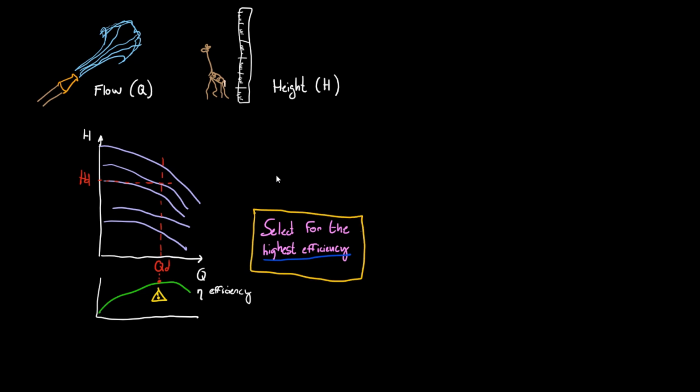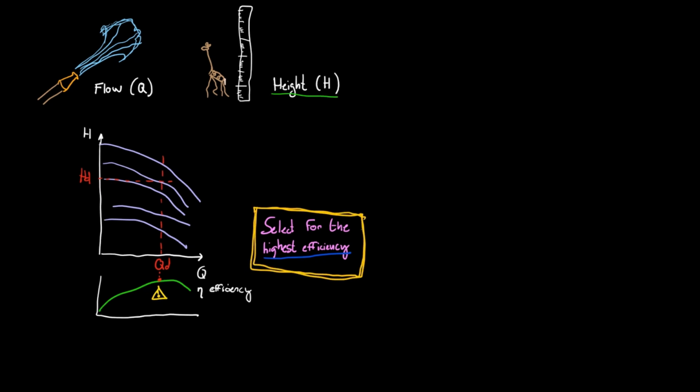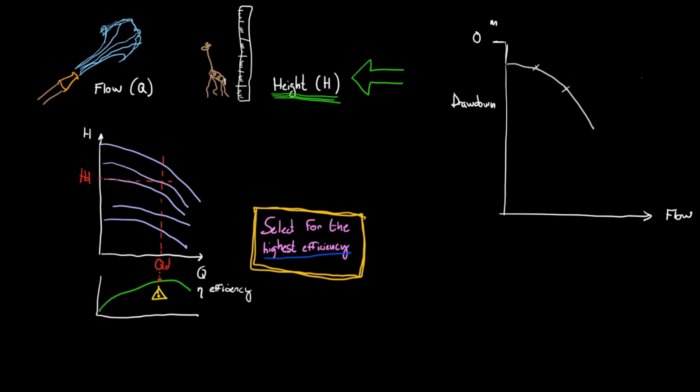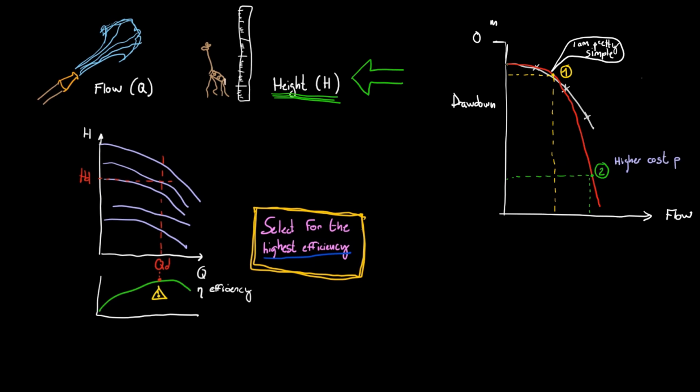The flow influences the head by either affecting the friction in pipes or the drawdown in boreholes. When dealing with boreholes, it is very important to minimize the drawdown by pumping very slowly. Beware of easy 3-point pumping curves. The curve that joins 3 points is the circle we often see in pumping tests, but the reality is not that simple. Pumping curves frequently have inflection points. Take a look at how pumping twice the yield in this case makes the drawdown head 10 times bigger for all the water. It may be more economical to drill a second borehole.